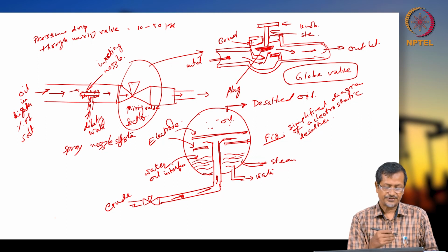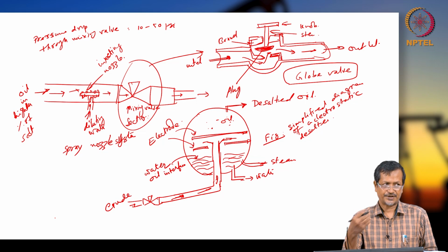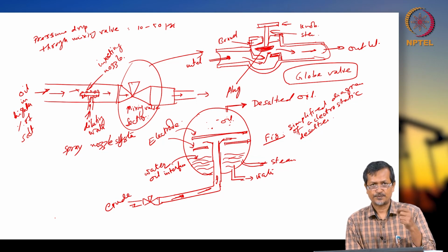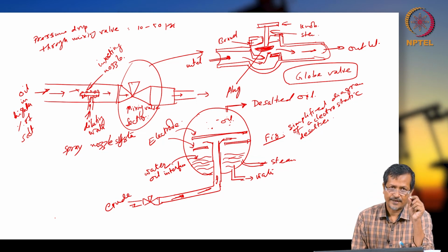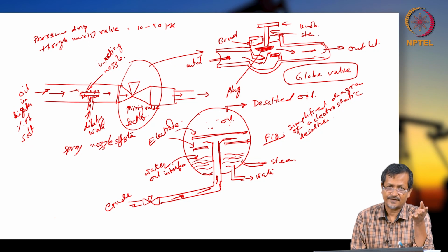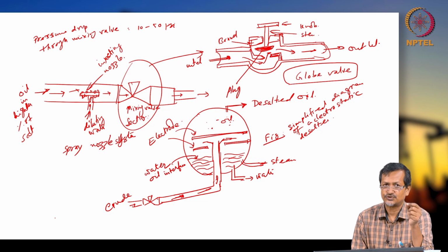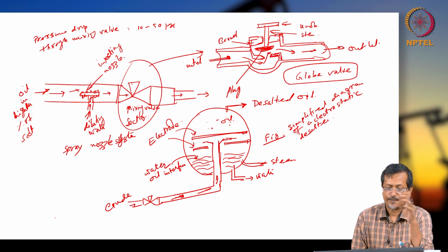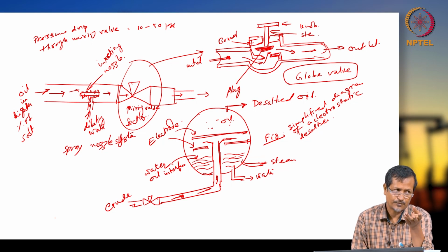So the valve will be shearing the droplets. Pre-mixing means you are mixing oil and water, but the valve will be shearing the droplets, making very small particles. But if the particles are too small, remember the settling formula Vt: too-small particles are difficult to separate. So that is also one negative. Your intention should not be to create very small particles, rather smaller particles, so that proper mixing is possible, and fresh water or low-salt water can interact with the higher-concentration water, and they can get settled out.